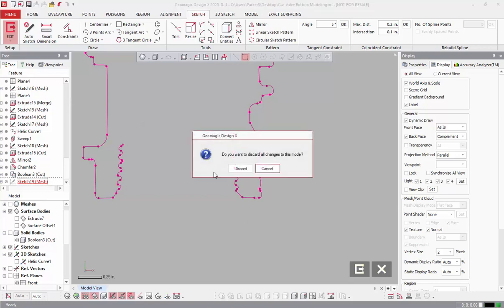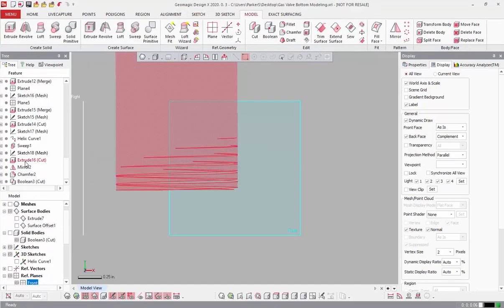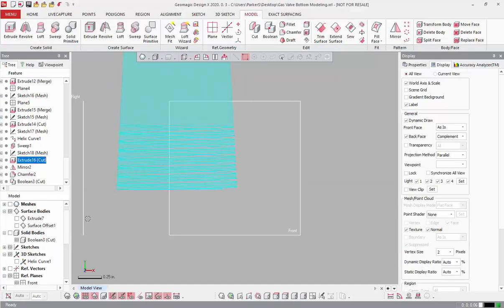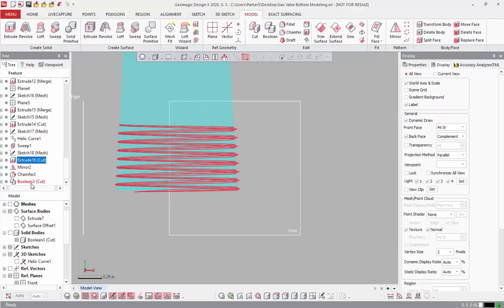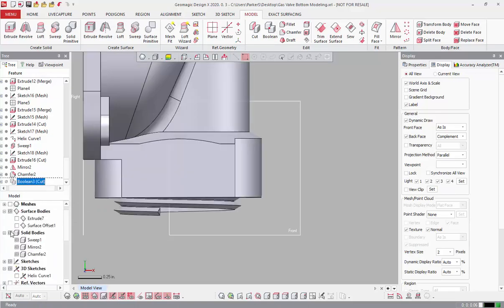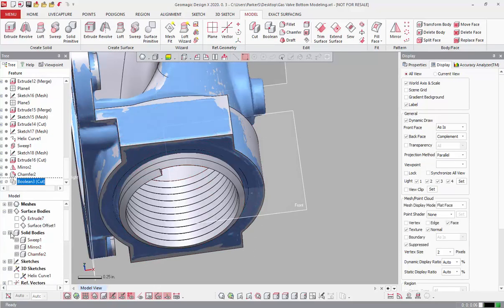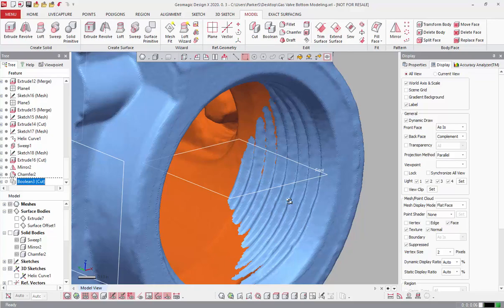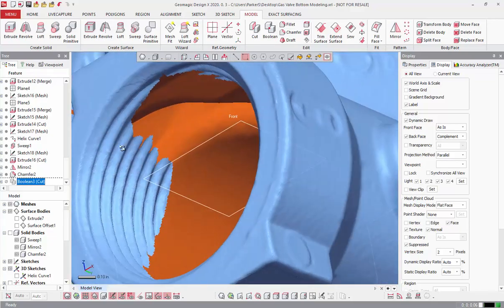So of course, before I do anything, I do need to go take a look at that extrude that I built, and we'll add the same draft to it that we had before, which I think we used 3 degrees. So that's going to make this a little bit more uniform, right? And then what I'm going to do, before we Boolean remove this, again, playing around with time manipulation here, is I'm going to just say wherever the scanner happened to see the last thread, we're just going to cut this off at that point.